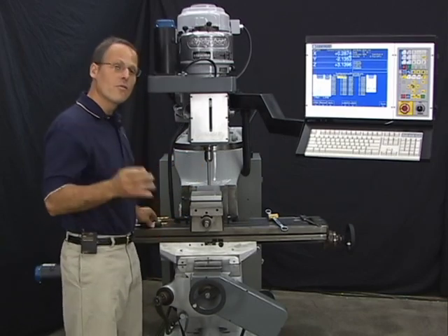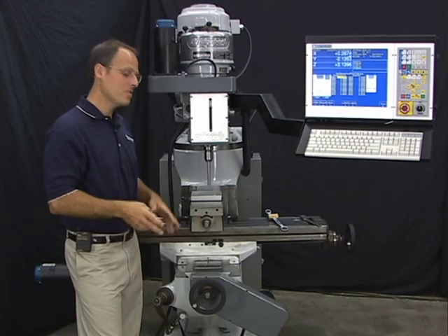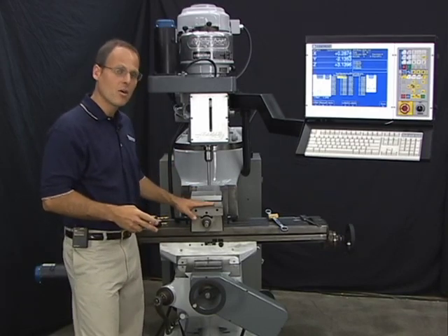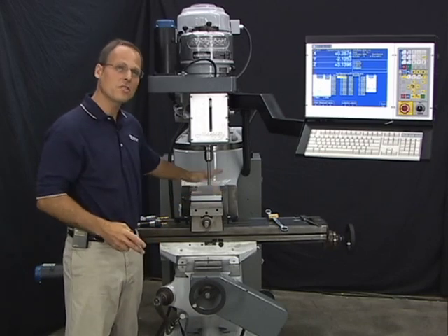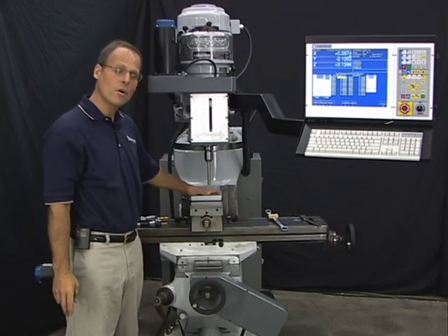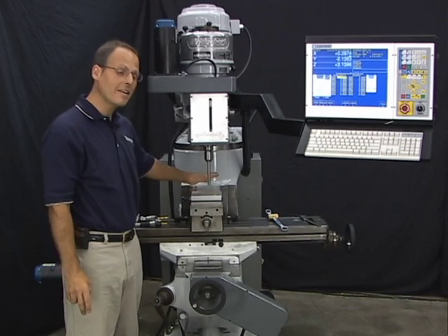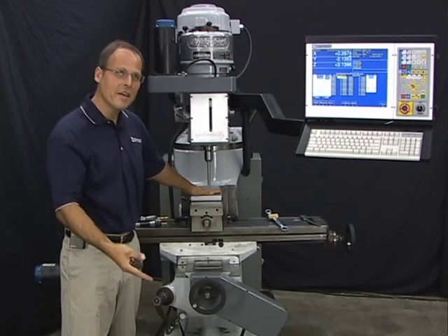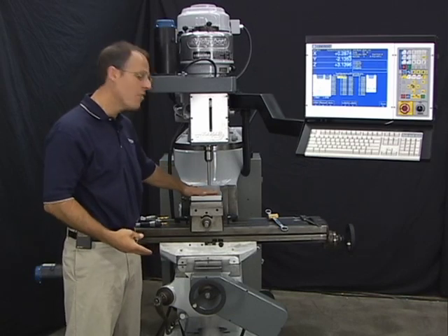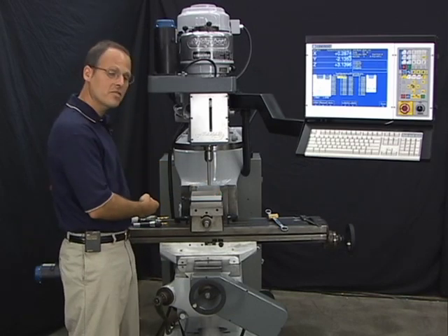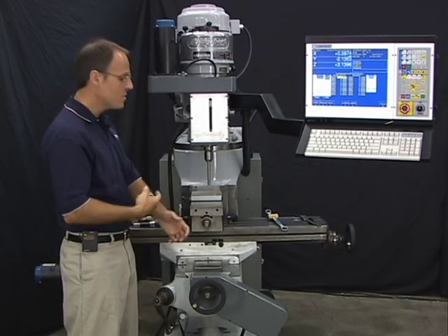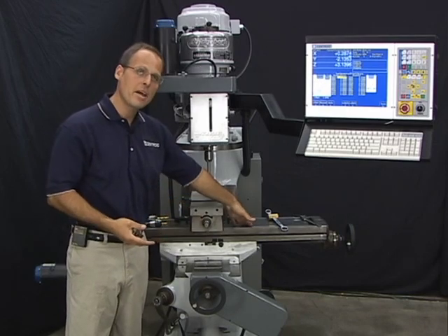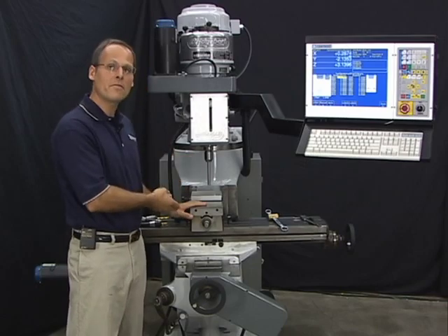Now, for a reference position, there are some better places than others. What I don't want you to do is use the top of your stock or the top of your workpiece. The reason for that is that it may be gone in an hour or the next day. Then I would have to reset that position again, since I don't have this position anymore once the stock is removed from the vise. So you want to pick a place that you can always get to, like the top of the table, or in this case, the top of the vise.